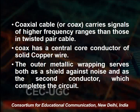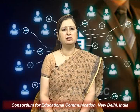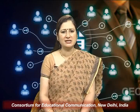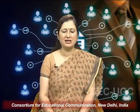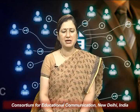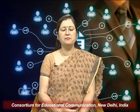So now in case of coaxial cables, the attenuation of course is much higher than in case of twisted pair cable, because the drop in signal is there, but they have a higher bandwidth, they can carry signals of much higher frequencies, but the signal will weaken rapidly, and therefore there is a constant need of putting frequent repeaters on the way of the signal. Why? Because a single wire is carrying it and high frequencies are being carried. So when you have a high frequency signal moving across the wire, then the attenuation increases.